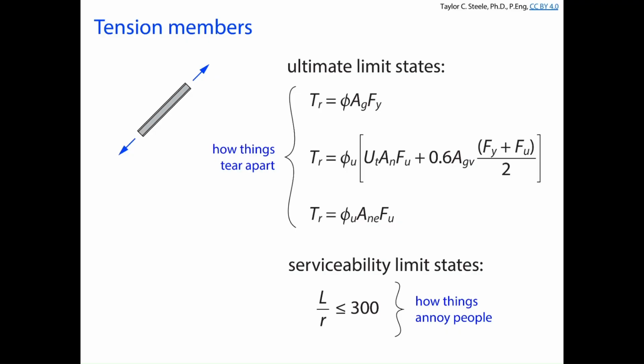We're pivoting a little bit though, because we spent quite a bit of time talking about bolted tension members. We would drill holes in the member itself to bolt the member to the gusset plate to make a connection. And when we did that, we removed some cross-sectional area and introduced some potential failure modes like net section fracture and block shear failure. Welding's not really going to change too much for us. We're still going to have to consider a net section, which might seem weird because we're not removing material, and we're still going to have to consider these other failure limit states.